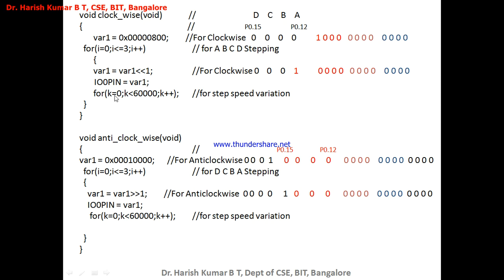Now A is energized, and I want to observe the step movement, right? Now this is the delay again, with the semicolon, you can observe here. After energizing A, the stepper motor will rotate by 1 step, and just to observe that, I am giving this delay. For every step the stepper motor stops and again goes back. So I is incremented, I is 1.